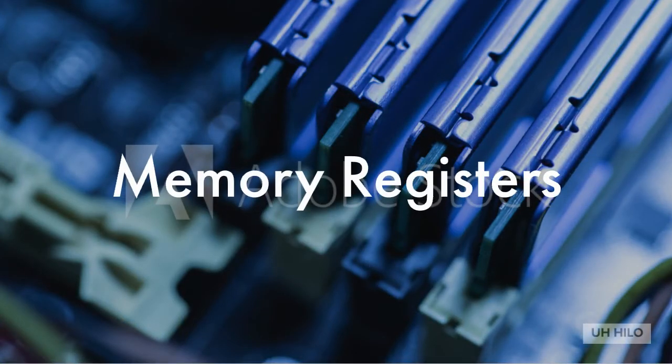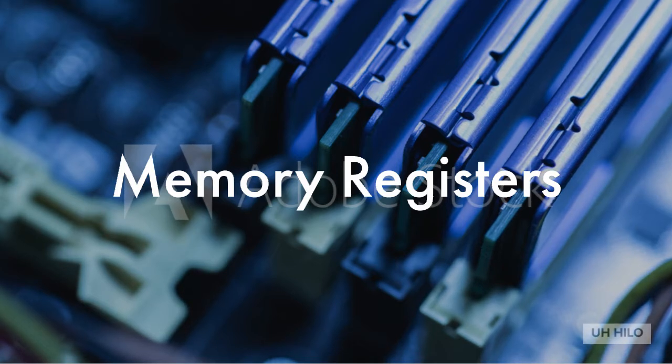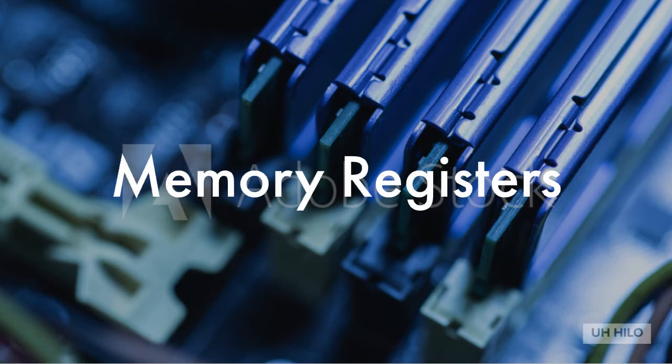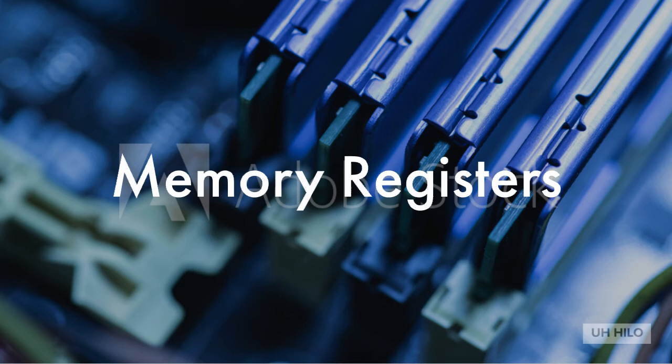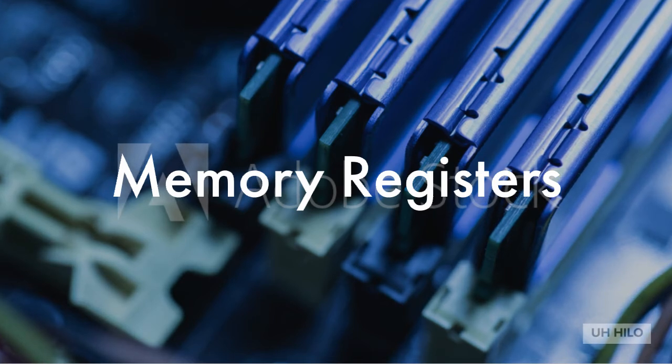Registers are special storage cells. In the execution of programs, we typically have memory address registers which hold the cell address. The address register should hold as many bits as there are in an address. There are also memory data registers that hold data values. These will obviously be some multiple of the memory cell width. Since W is usually 8, the memory data register could be of size 32, 64, etc., since values are typically larger than 1 byte.